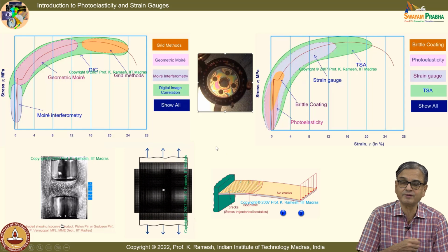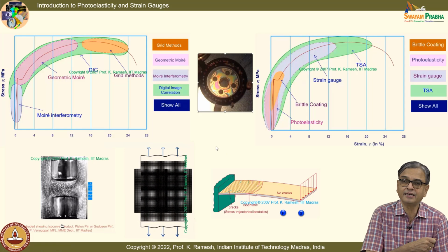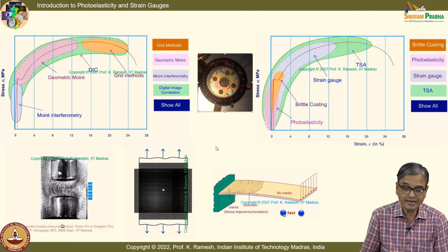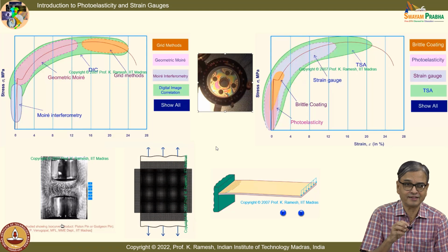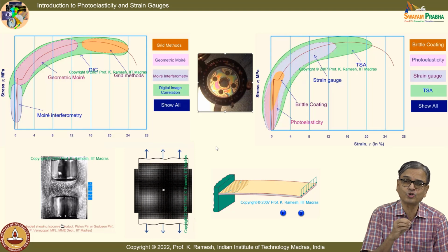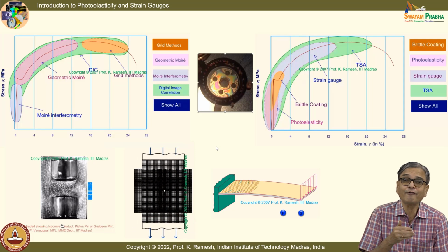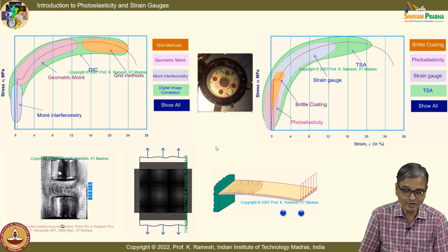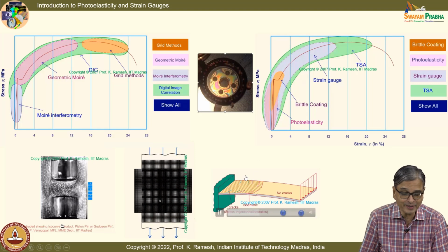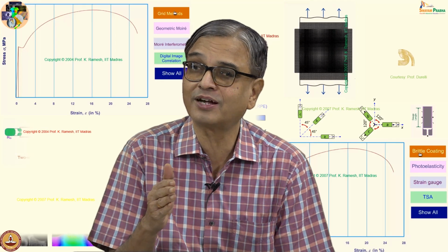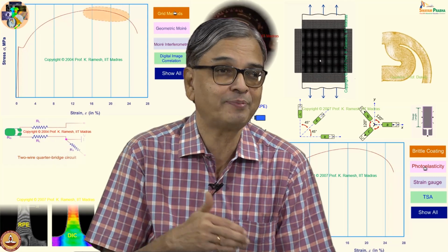We have said that we will spray a brittle material, and it's very interesting. It's a brittle material, so when the normal stress reaches a critical value, you have cracks formed. So, in this technique, cracks are information. Normally, you are worried about the crack developed in any structure.